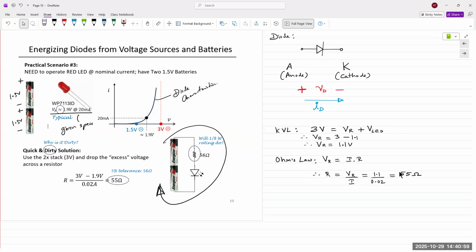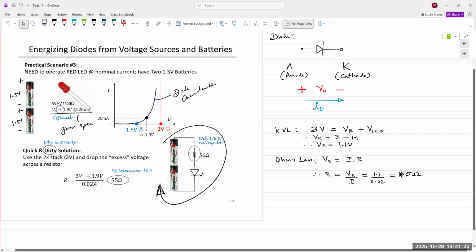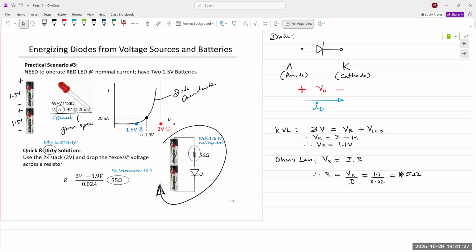We don't need to have a resistor for those kind of circuits because the battery is so small that the current supplied from that battery is going to be very small. But it might be just sufficient enough to turn the LED on. As I said, it's 3 volts. You're applying 3 volts. It's going to source some current, but you can do this even without a resistor. It'll work. It's not going to harm the diode or LED.